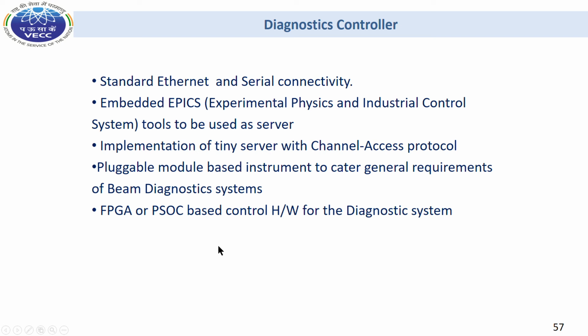So we have chosen a very small footprint EPICS server. It was implemented with the channel access protocol. The tiny EPICS was embedded in the communication controller. The communication controller is a pluggable module based instrument to cater to general requirements of the beam diagnostic system. We used ARM based or FPGA or PSOC based communication controllers as the embedded EPICS controller.